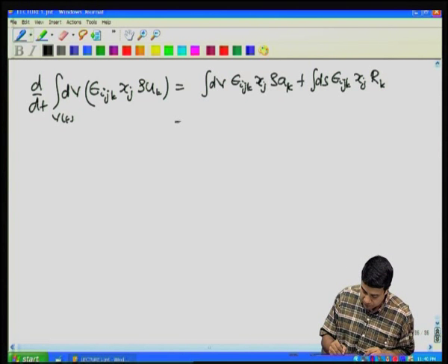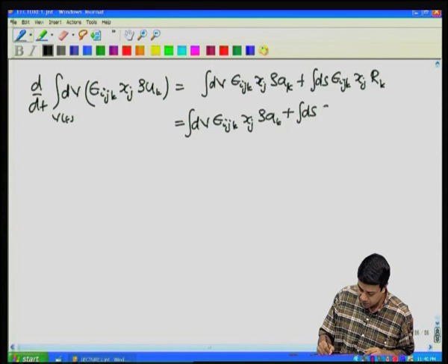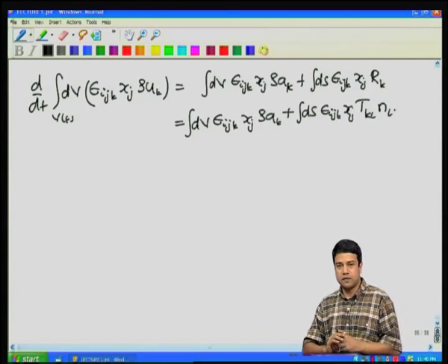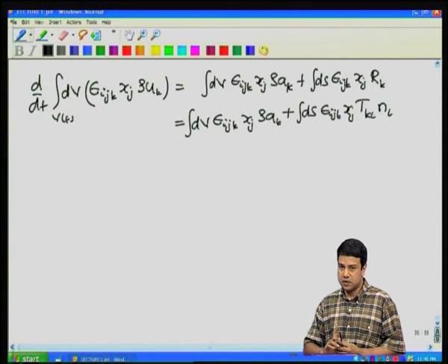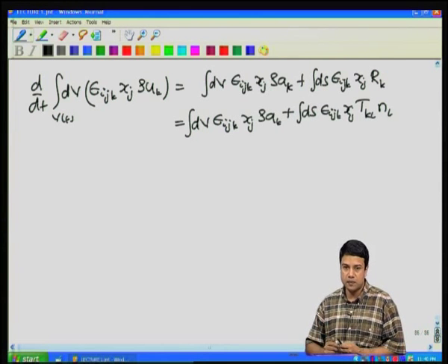And from my expression for the surface force in terms of the stress, I know that this has to be of the form epsilon_ijk x_j t_kl n_l. It has to be of the form t dot n, and I have to choose indices which are new for each dot product, because if I use the same index j or k for this last dot product, that index would appear more than two times and it would result in an incorrect equation. Okay. So, simplify the left hand side first.